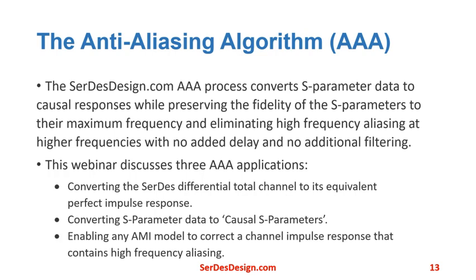This webinar discusses 3 anti-aliasing algorithm applications: converting the SerDes differential total channel to its equivalent perfect impulse response, converting S-parameter data to causal S-parameters, and enabling any AMI model to correct a channel impulse response that contains high-frequency aliasing.